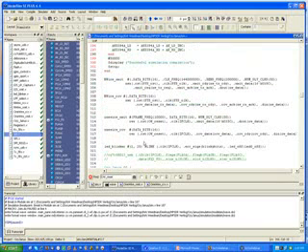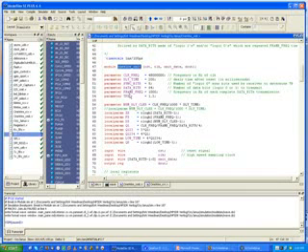So now, let's go back. I'm telling it I want to receive 16 bits. Now in the transmitter I said, okay, I want to transmit just 16 bits too. So I want to do a similar thing. And there's another parameter I wanted to override so it didn't take so long, so that it sends out this sequence every 10 kilohertz. Those were parameters in the transmit module right here, frame frequency. And so that's why I put these right here at the beginning.